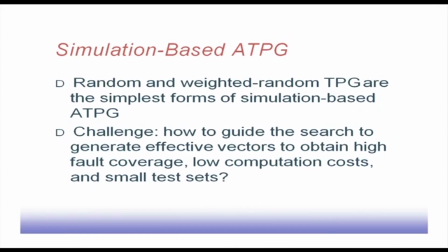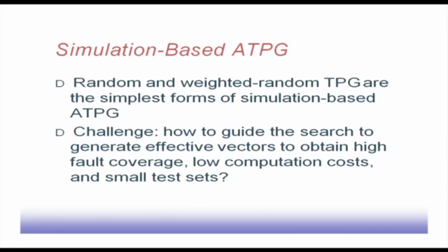Another class of ATPG algorithms are known as simulation based ATPG techniques. So far, among the techniques we have discussed, one of them was the exact method like Boolean difference. Then we have seen a number of heuristic methods, like D algorithm, PODEM, FAN, etc. Now, another class of ATPG algorithms are known as simulation based ATPG algorithms.